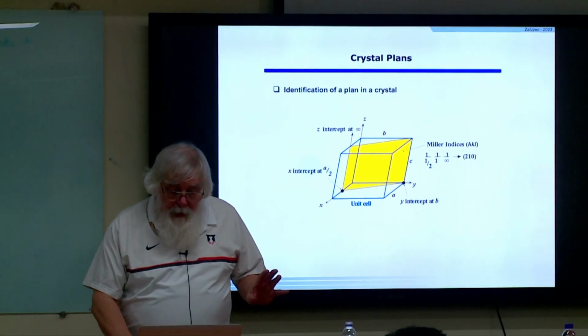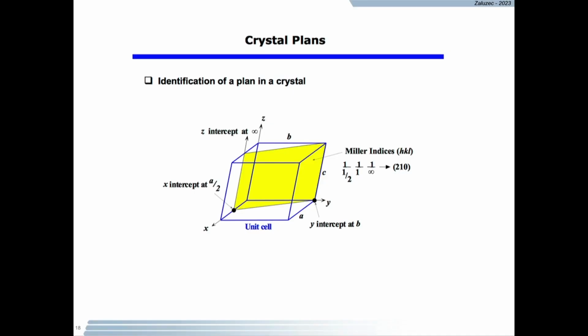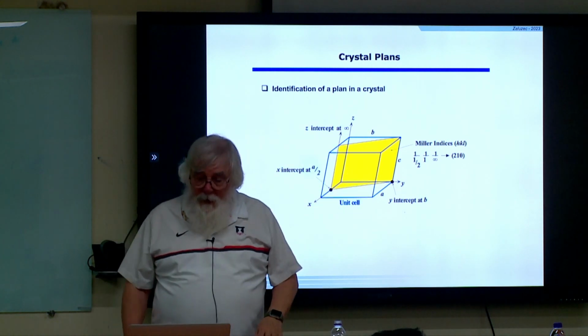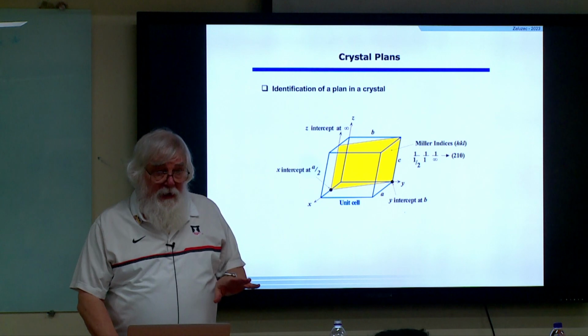The other thing to realize is that when you have crystals, crystals with a very specific structure, we can describe those crystals as having planes of atoms. I'll talk about planes quite frequently. I'll say this is a 110 plane or a 111 plane. That has to do with the description of where that plane goes through that crystalline lattice. Again, if you've got a question on that, let's talk about it later.